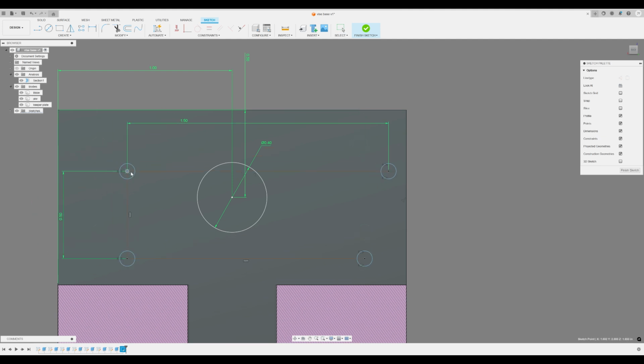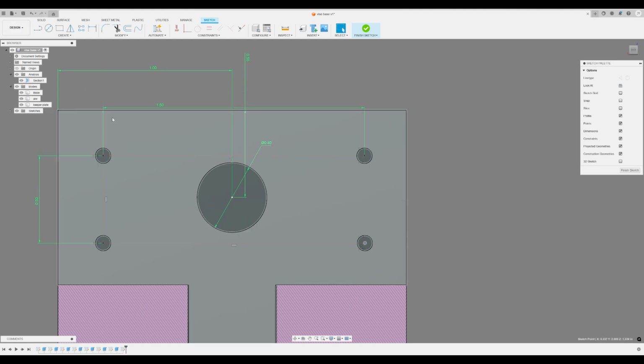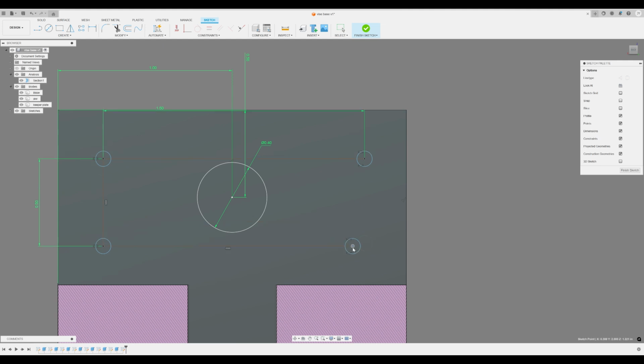All right, so if we don't know where the constraint is missing, we can grab any of the blue lines, tan lines, and drag them, see what happens. And as we can see, it can move up, down. Also, this one is not defined, so it can move in and out because I only did 3 lines, not 4. So I'll add a 4th line in there and do a horizontal vertical constraint.